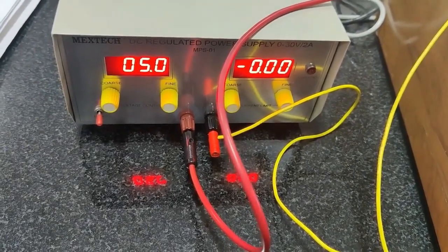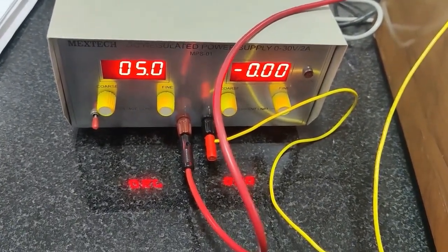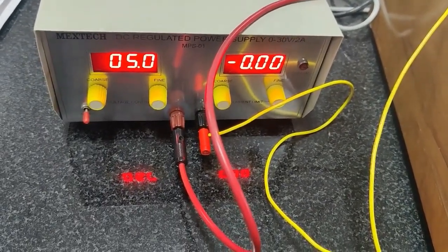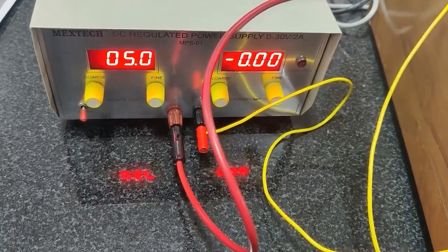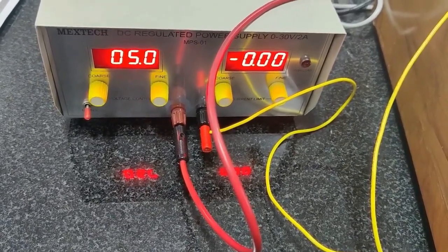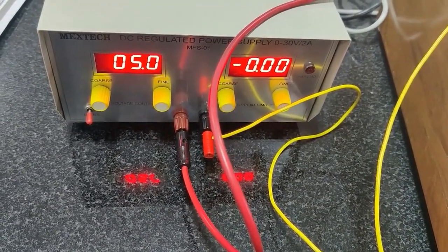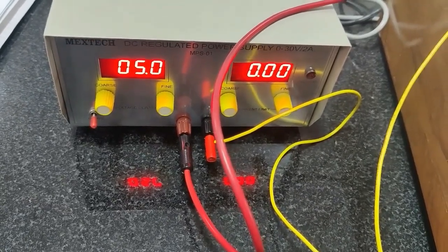As we learned last time, instead of charging in one step, for example from 0 to 10 volts, if we charge in two steps, 0 to 5 volts and then 5 to 10 volts, the energy dissipation will reduce to around half of the previous value. We have to verify this claim.